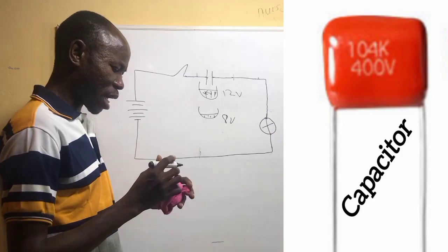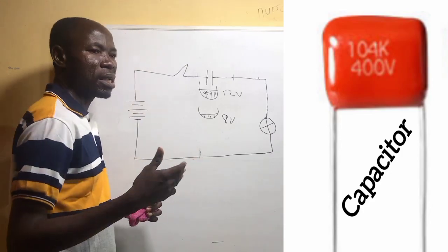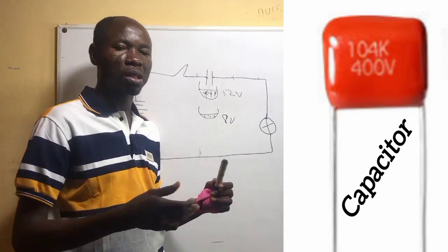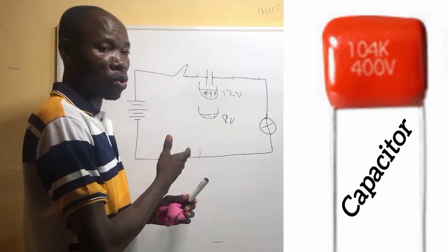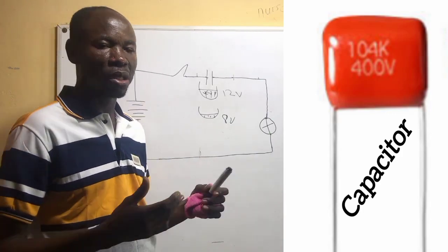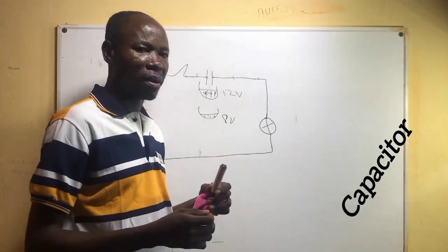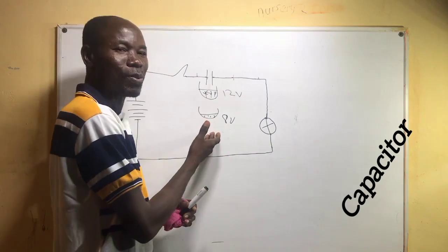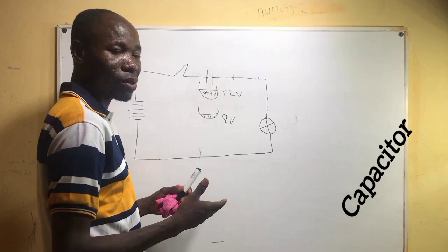And the leakage capacitor is very difficult to find sometimes. Sometimes when you switch your machine on, it can come on. Later when you switch it on, it will not come on. Most of them are caused by leakage. Even sometimes it can be caused by a dry joint or improper soldering of the component, but most of the time it's caused by leakage capacitors on the board, because the capacitor is meant to store electric charge.